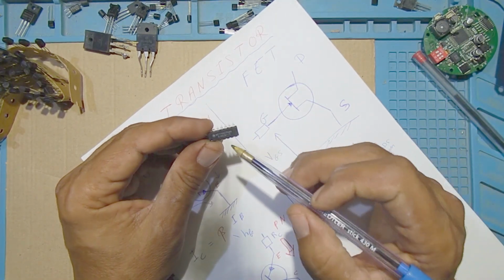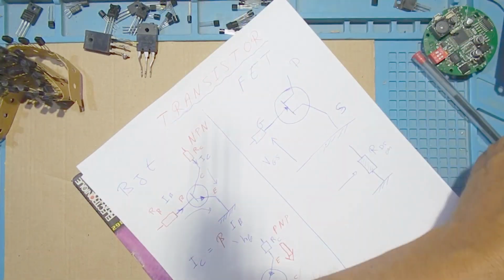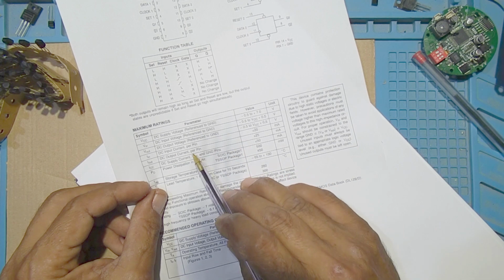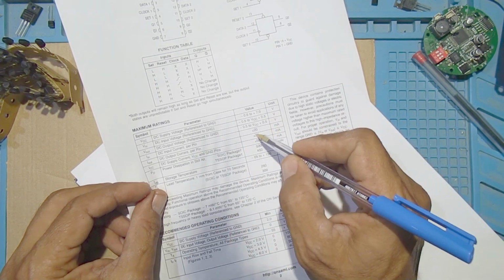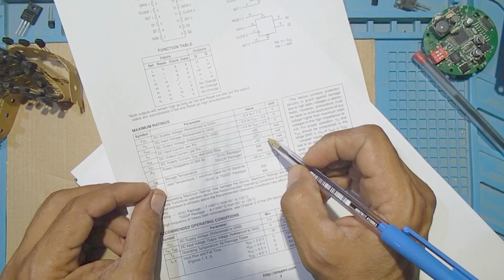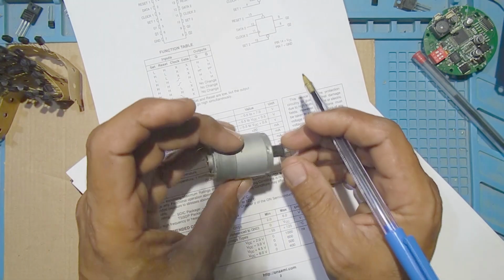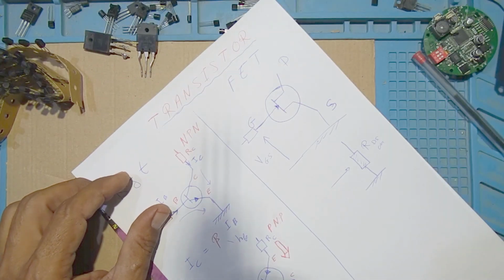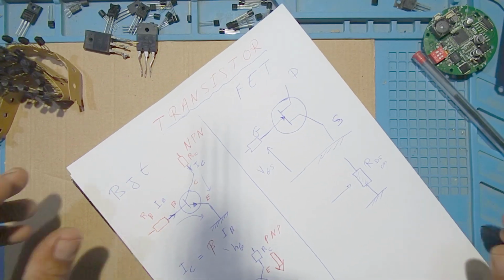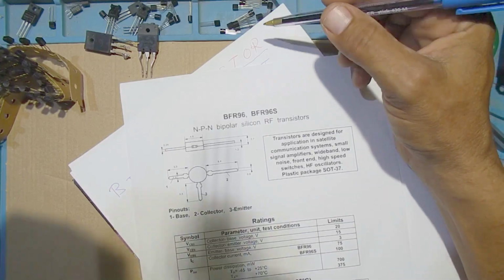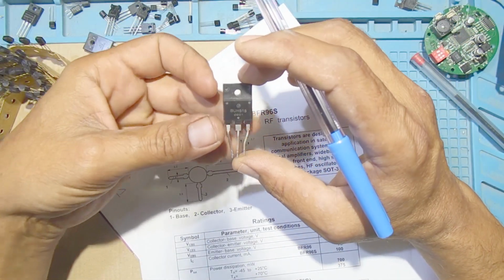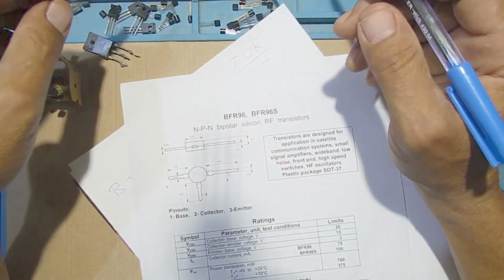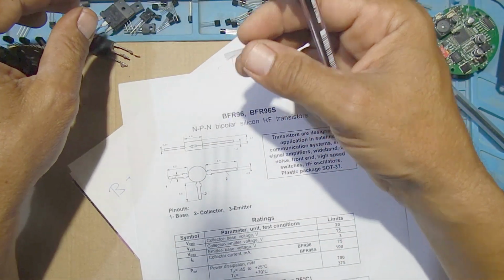For example, this circuit is 74HC74. We can see the datasheet of the circuit. The maximum current that it can source or give is 25 milliamp. 25 milliamp can't activate this motor, for example. So we need to use a transistor. The transistor used depends on the amount of current we need, or power. For huge power we need this package, and for small power we need those tiny transistors.